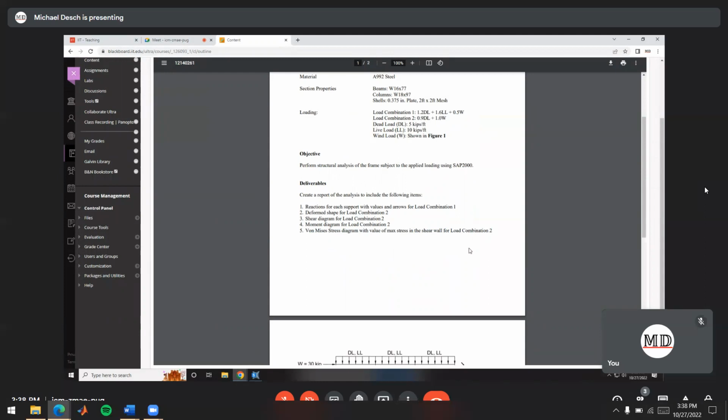And then those are pretty trivial to translate into the bending stress or the shear stress. We have those equations from your mechanics of materials class, My over I, VQ over Ib for the shear stress. Axial is just the force over area. So that's easy.